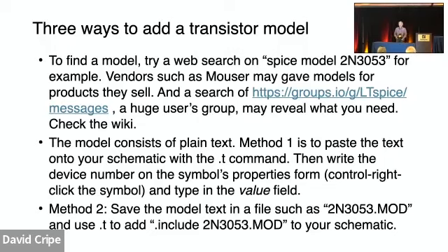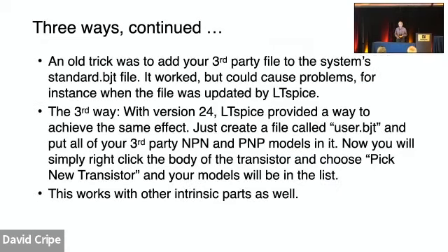And, you know, no sense in having a single file, so you create your own file. Well, we're going to talk about that. An old trick with LTspice was to take your transistors and paste them into the component databases that the system gave you, so it looks like it's part of the system. But they discourage that because LTspice updates pretty often, and when it updates, it overwrites that, and you come back 6 months later and you go, hey, it won't run. I can't find my transistor.